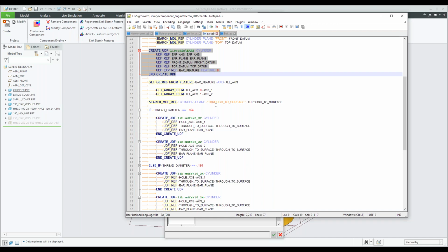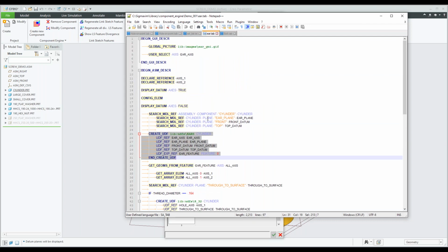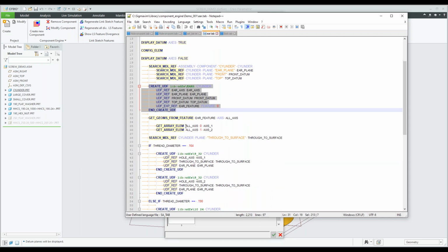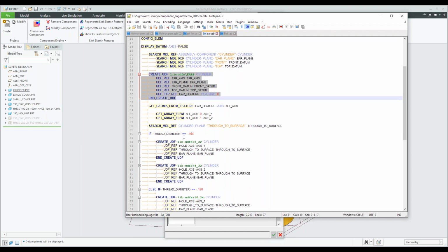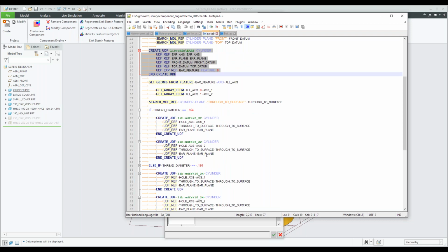So you'll see there were different options that I could choose when I created the ear product, and I'm just telling it if it selected a certain reference, then run this UDF. So you can see fairly standard if statements, and then from there you're just reusing information that was already created in Creo. Okay, so before I confuse you even more, let me start by explaining what a UDF feature is.